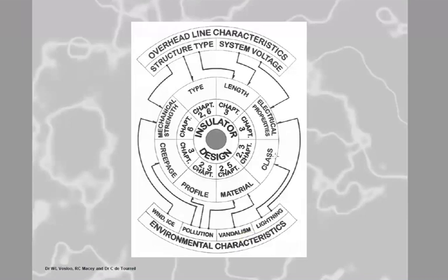structure. Then the electrical properties, again, obviously, are also determined by lightning. So that electrical property is going to say, I want a BIL of this. Now you need to think, at low voltages, below 245 kV, you're normally looking at lightning as being your issue. When you go above that, you start looking at switching impulses as being your issue. So you need to look at the electrical properties of what you determine from this insulator. Also, you do arc resistance tests, where you do a power arc test across the insulator surface to look at where the insulator can withstand different electrical aspects of it.